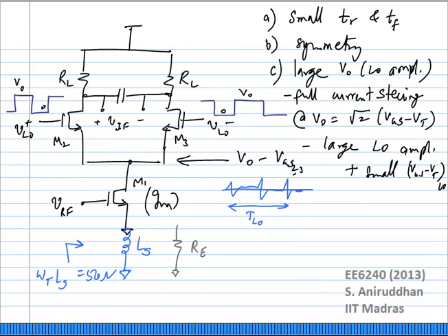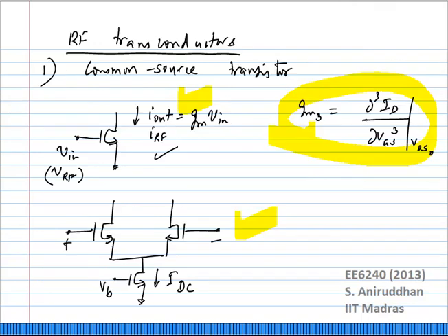So if you take this transconductor, you need to understand first of all the bias point. The gate bias point can be easily defined, right? If you define the gate bias point and this current, the VGS of this transistor is defined and the VDSAT for this current source is defined.